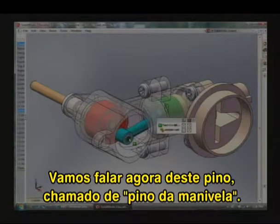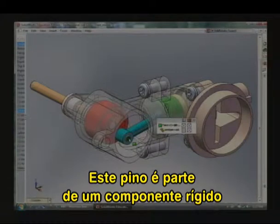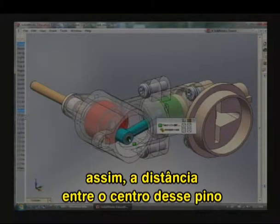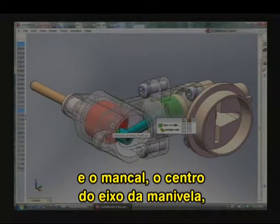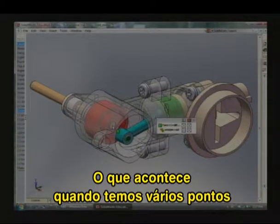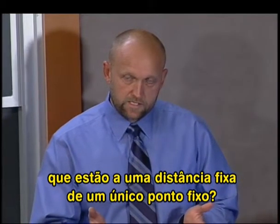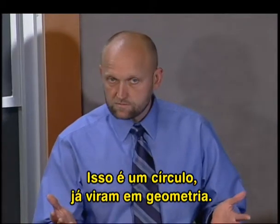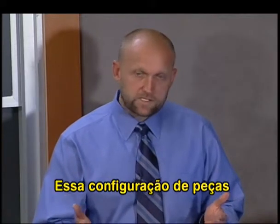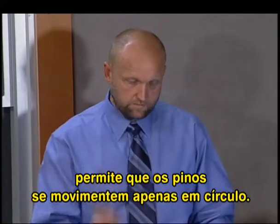All right, now let me talk about this pin here. This is called the crank pin. This crank pin is all part of one rigid component called the crankshaft. Therefore, the distance between the center of this pin and this bearing here, the center of the crankshaft, is fixed. So what happens when you have a collection of points which are all one fixed distance from a single fixed point? Well, that's a circle. You know that from geometry. So this configuration of parts allows the pin to move, but only in a circle.